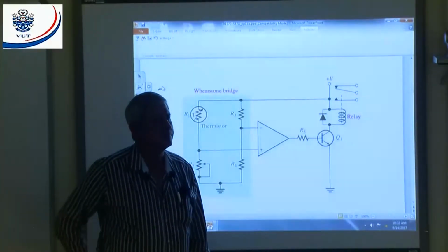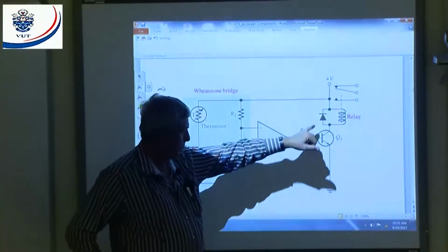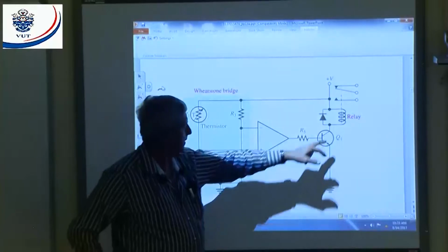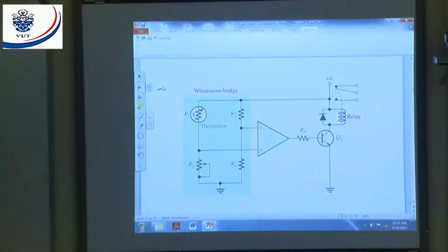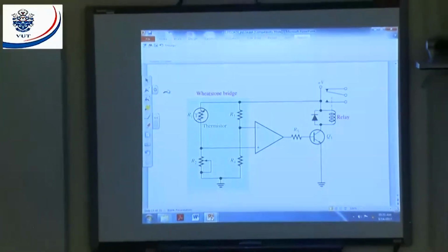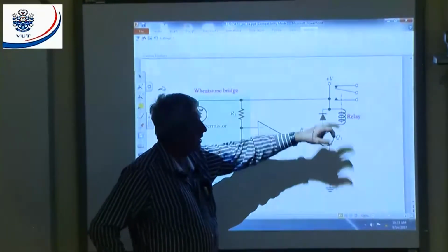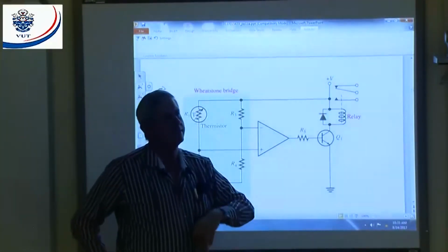When this transistor turns off, here we have a magnetic flux. You know what a magnetic flux is? Now we go back again to Engineering 1. When that magnetic flux collapses, it cuts the conductors, and it can generate an EMF that's much higher than my supply.